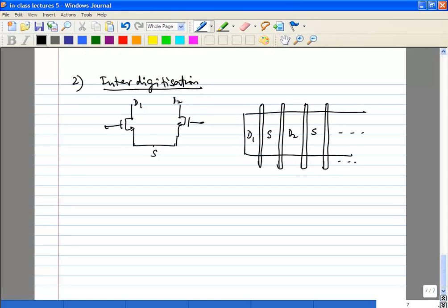In the earlier case, we looked at multiple fingers being used for a single transistor. Here, if two transistors, for example, share a common node, in this case a common source node, you may want to reduce the parasitic capacitance at this node. Remember that for the mixer, classic example. If these are the switches, you want to reduce the parasitic capacitance. So for those switches, you're going to share the sources. Drain capacitance, you don't care too much because you're actually having an RC filter for a receive mixer. So you may want to do something like this.